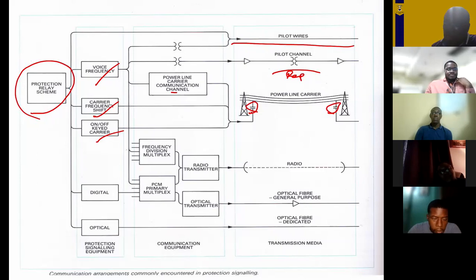Or you can do the multiplexing, which is basically creating your own communication system, and you transmit it via the antenna. So this would be microwave here. And the pulse code modulation can be done either via radio or optical, which is why the transition at JPS, for me, was not so difficult, because the main method they were using up to a few years ago was microwave.